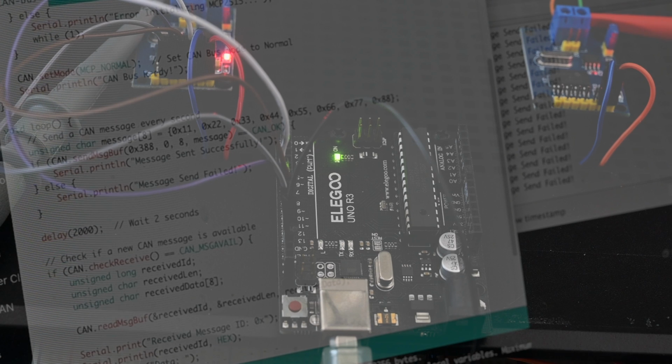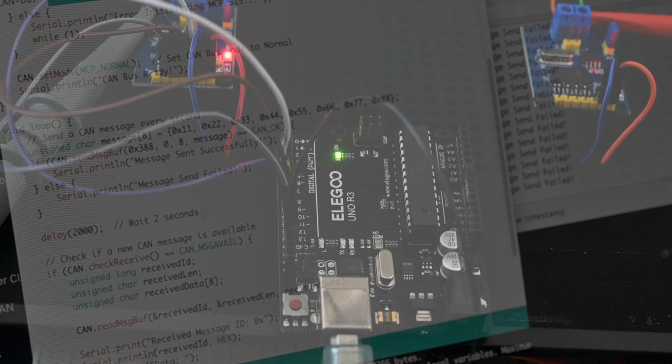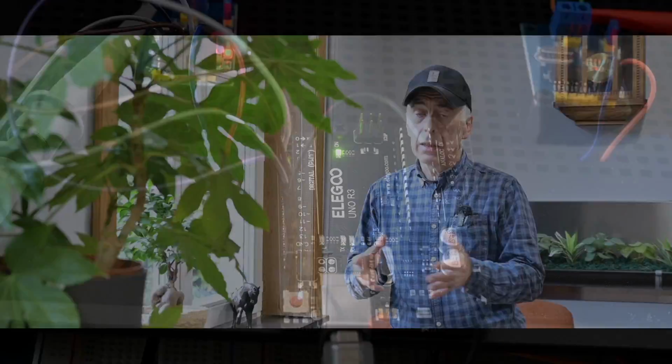What I've shown you is one example of how a digital phase-lock loop system works on CAN controllers. Now, of course, if you're going to develop your own CAN controller, you will have to check out what the datasheet says about the specific chip you're using for your CAN control. And then you have to make sure that you know all the parameters of the design constraint within your entire CAN bus system. Can you set all this up, and can you actually see this on the CAN bus when you're putting an analyzer up?